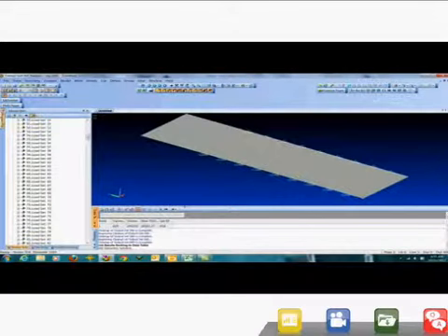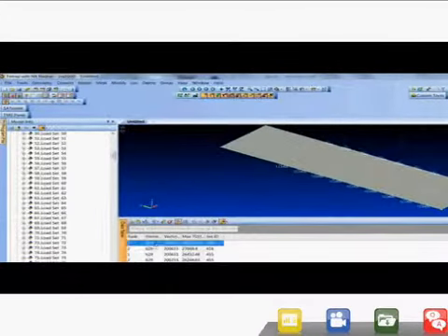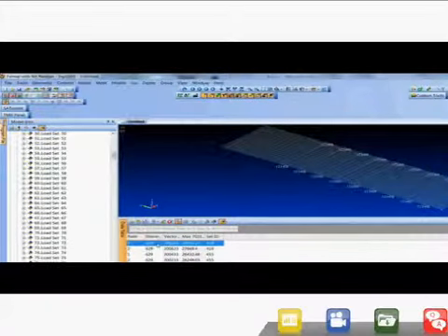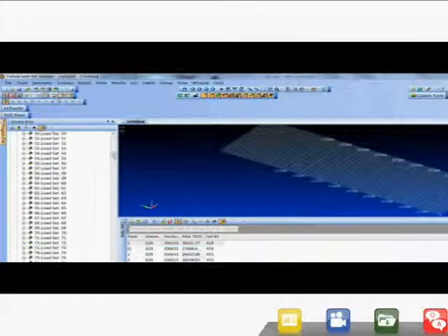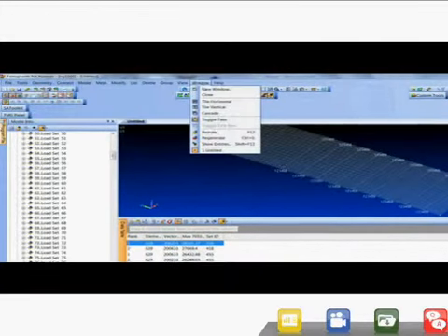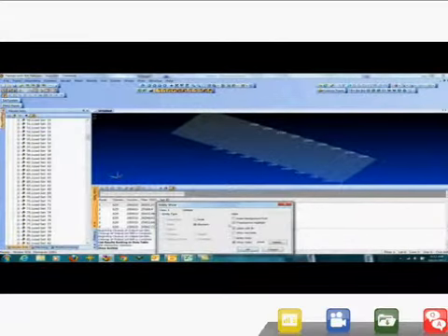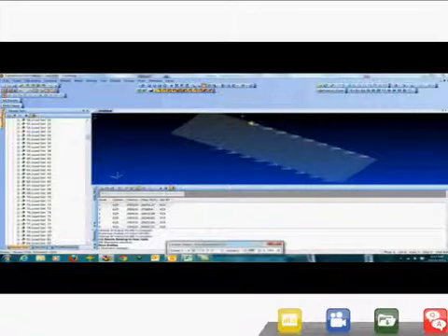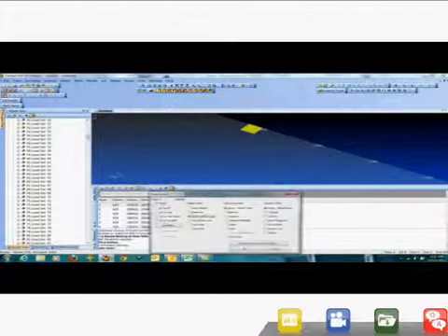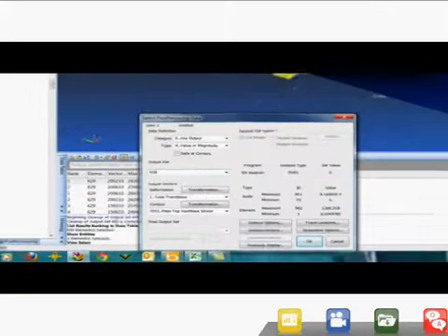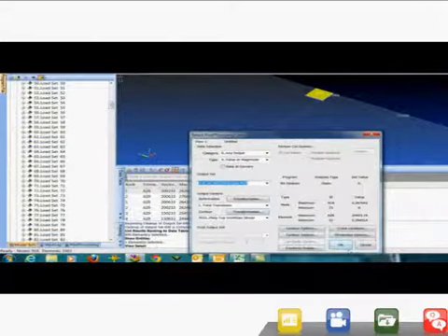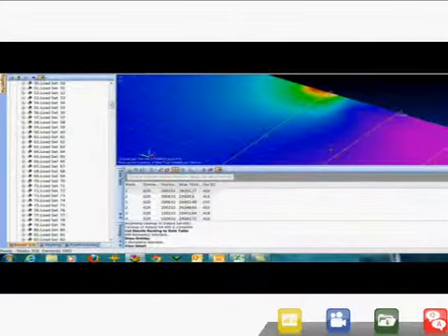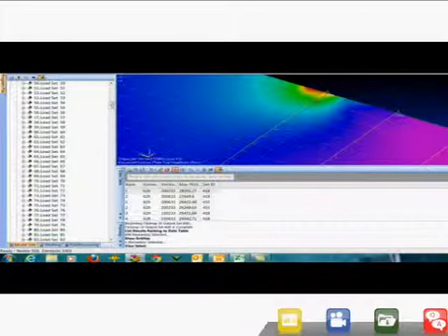And I can actually turn on the highlighter here and have FEMAP show me who element 629 is. So, oh no, it looks like the rank is coming out there, so it's not showing it to me. But window, show entities, element 629. So there's my worst von Mises stress, and I know it comes from output set 418. So then we could go in here and just take a look at that. Let's change this to 418. It's got von Mises stresses. Say OK. And there's our picture. Must have that little load right there. So ranking is pretty easy and pretty straightforward.